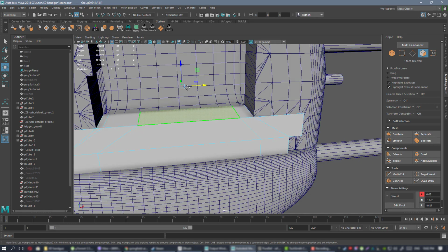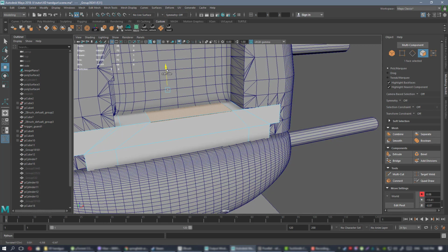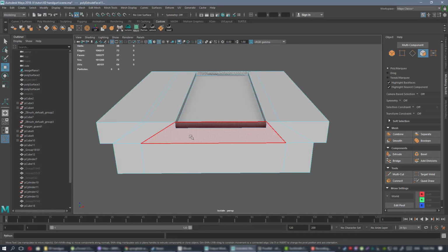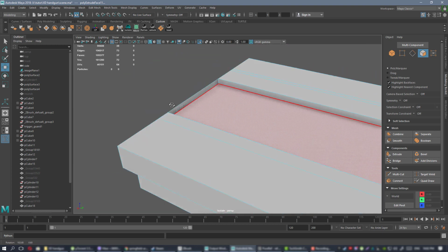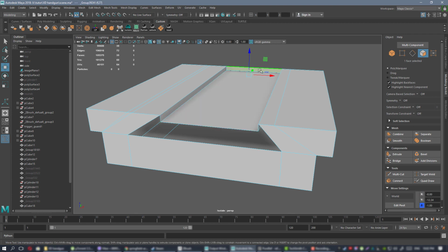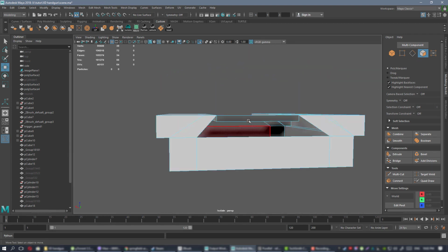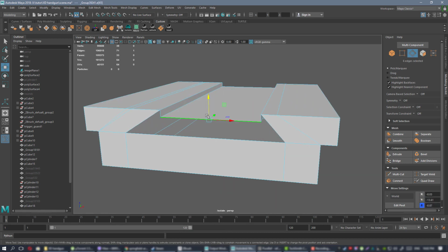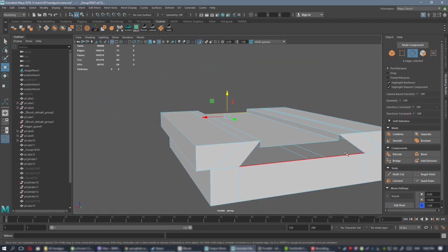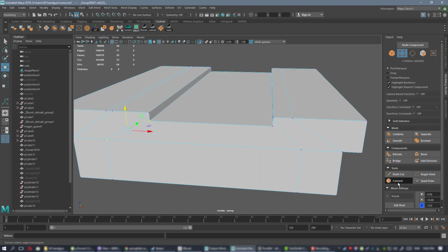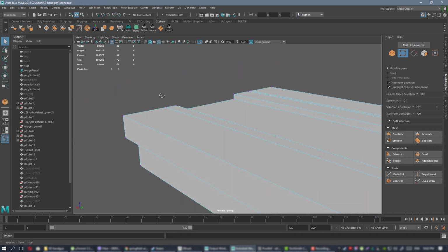Move this guy to the side, and extrude inside just a bit. And you can see there's an issue over there, because we have struggling faces, this face and this inside face. So in order to fix that, just delete those guys and reconnect them. Turn off the ambient occlusion. Just close hole here and close hole here, and just reconnect the points right there.